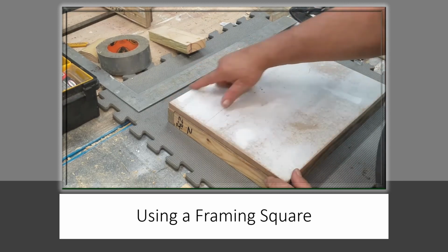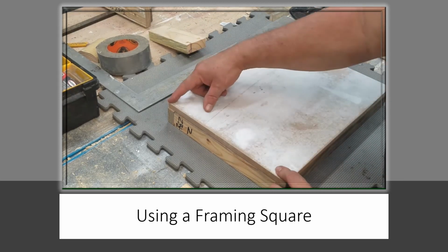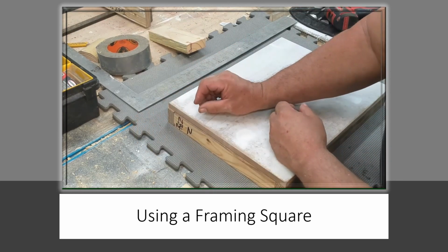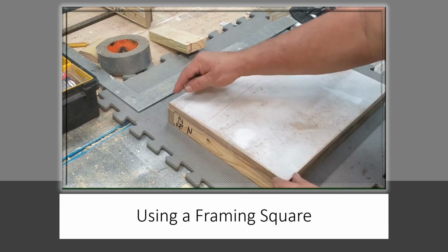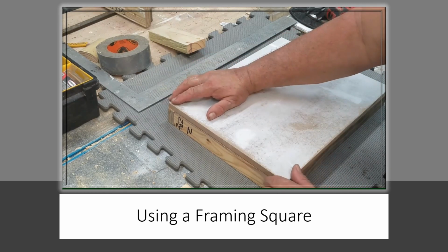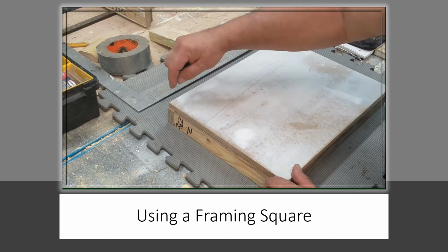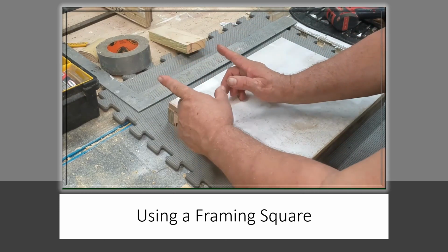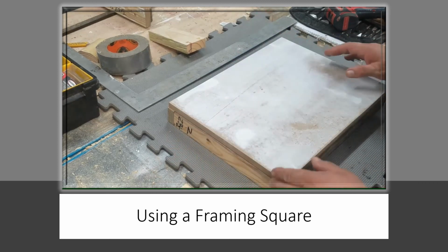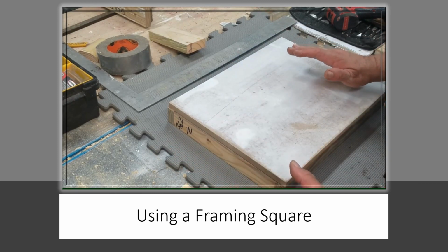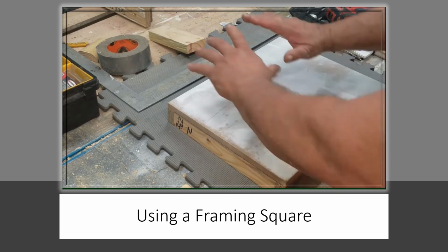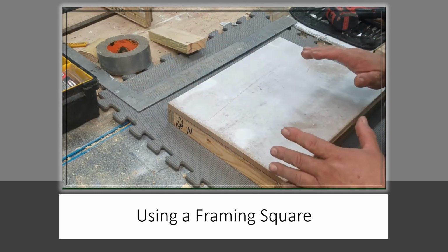This is a small area. This is 12 inches wide. How far off is that? Only about that far. This is 1 foot wide. What if your house is 30 foot wide? Multiply this amount by 30. It could be way off. So nothing is going to fit right. So you got to make sure everything's 90 degrees, because as the project gets bigger, so does the problem.